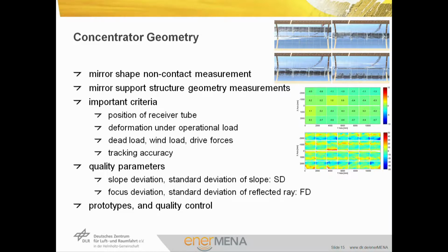quality parameters. Important criteria are the position of the receiver tube, it must be in the center. The deformation under operational load must be low. Wind loads, dead loads, drive forces must be kept low. And the tracking accuracy is important to reach high performance.